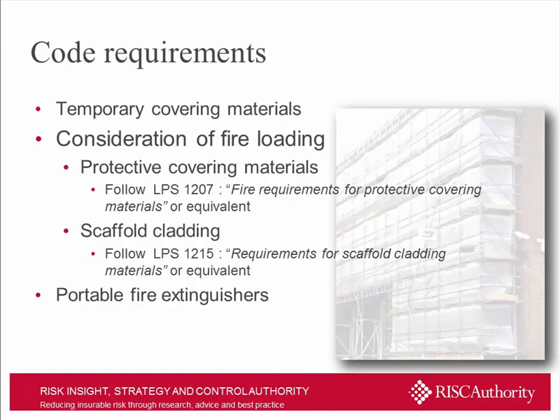Dealing with a couple of more specifics and things that I think are important, the code makes requirements for the use of temporary covering materials, obviously in circumstances such as we were just discussing at Minster Court, where you've got significant volumes of scaffolding, or where there's an awful lot of finishes that need to be protected, particularly towards the end of a project. The use of temporary covering materials is quite common to ensure that finishes don't get damaged, or in the case of scaffolding, that stuff can't be dropped off a scaffold onto the public passing beneath.